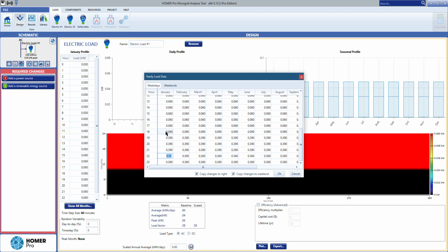Okay, so afterwards the final load is one TV set of 100 watt operating from 8 p.m. until 10:30 p.m. Again, I don't have 10:30, so I can enter it until 11 o'clock again. 100 watts, so 0.1 should be added from 8 p.m. to the rest, so it is 0.490, exactly 0.490, and then this one is 0.460, and the last one also 460 watt.